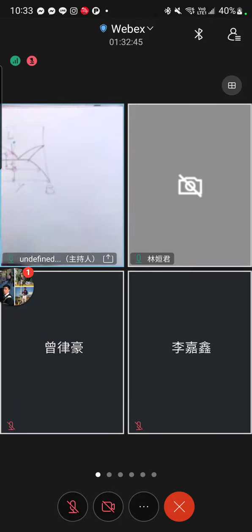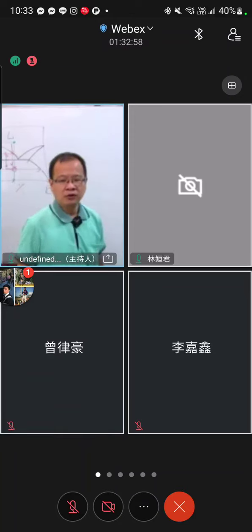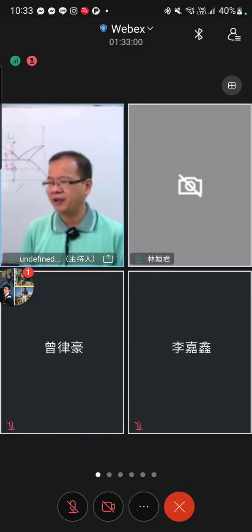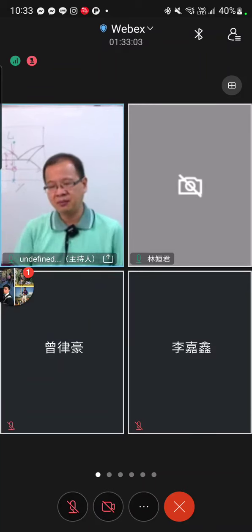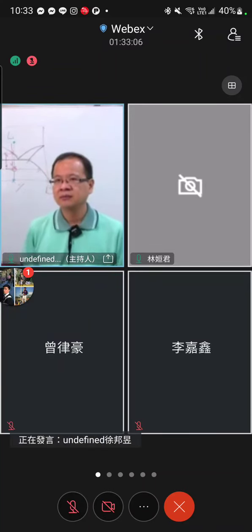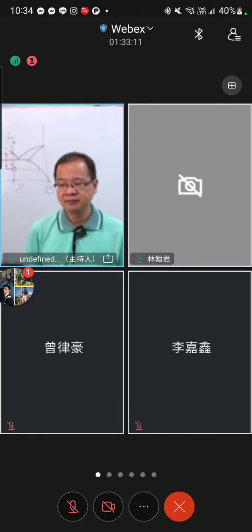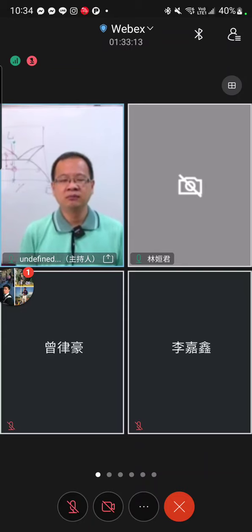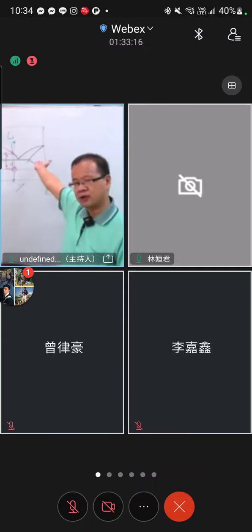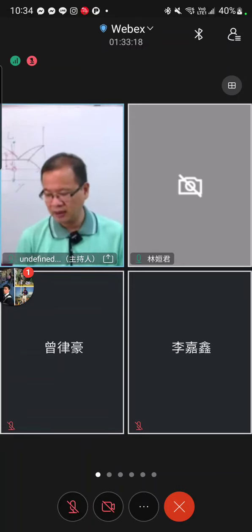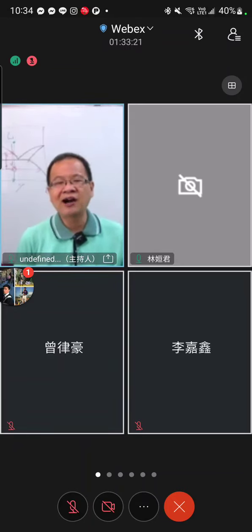and that's kinetic. But you have the thermodynamic map, phase diagram. So you know your start, you know your end, but the path depends on you. Okay. So you can use a different kinetic mechanism to limit the precipitation or limit the diffusion, changing the concentration, and then you may or may not reach the final target in different ratio, right? So that's how you combine thermodynamic and kinetics and lead to your target.